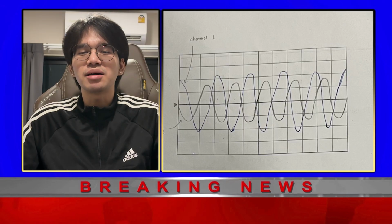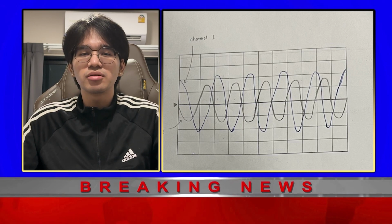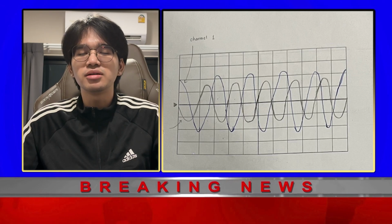To measure the time shift, as you can see, there is a gap between the 2 waveforms which is equal to 1 division or 5 milliseconds. To calculate the phase shift, we need to use the time shift divided by the period and multiply by 360 degrees.